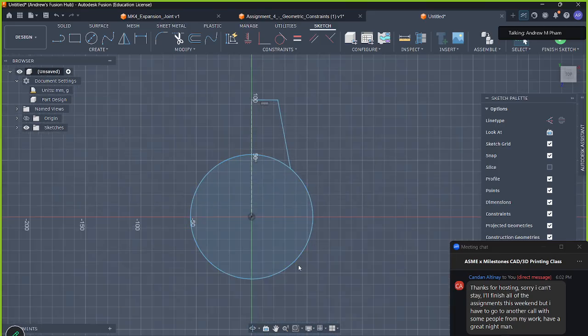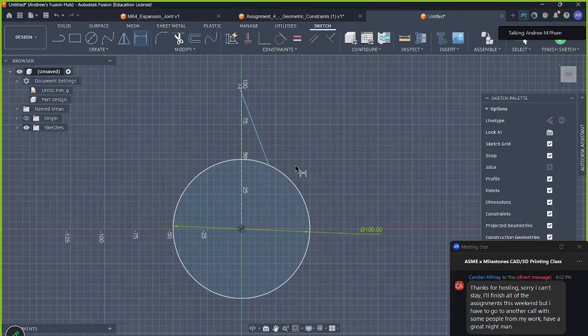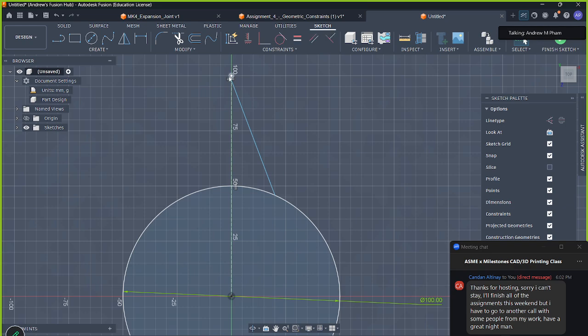So in this case, I'm going to define the diameter of the circle, the length from here to here, and then the angle of the gear, and also the height. So we've applied some geometric constraints, right? That horizontal line there, or horizontal constraint there. But now we can do the rest with dimensional constraints, just like week 1. So over here, sketch dimension, and I'm going to start applying constraints. So 100. Again, your numbers don't have to be exactly like mine.